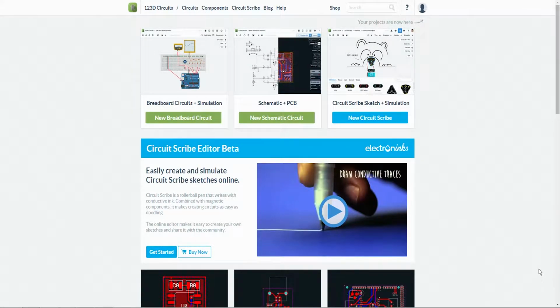going to use a 220 ohm resistor, as far as what the book says, because in the book he uses V=IR, which is Ohm's law, and then he uses the power formula, which is P=VI, voltage times current, in order to find out how to get an LED to run safely in its power consumption, because power is what destroys circuits. So a lot of these circuits that we do in the emulation will run exactly fine in the emulation, but when you try to do it in real life, you might burn up a part.